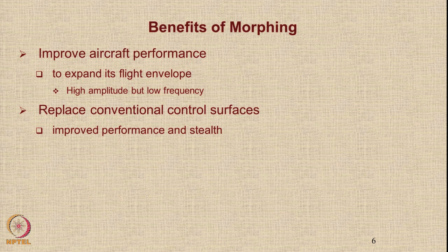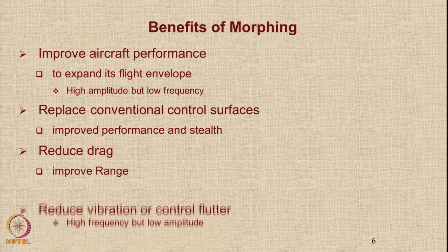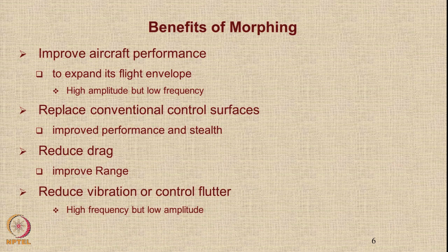Another application of morphing would be to replace the conventional control surfaces so that we have improved performance and stealth, or we could reduce the drag, which leads to an improvement in the range. The other application of morphing could be to reduce vibration or flutter or to control the flutter. Now here we have high frequency but low amplitude, that means we morph almost all the time, but the amount of morphing is very small.